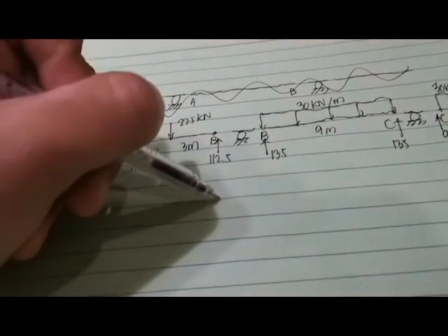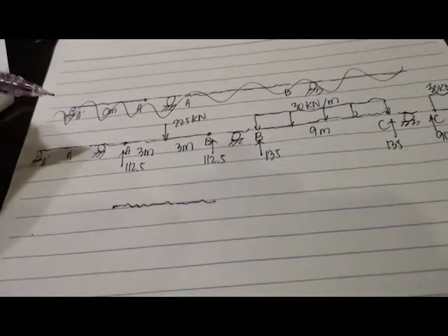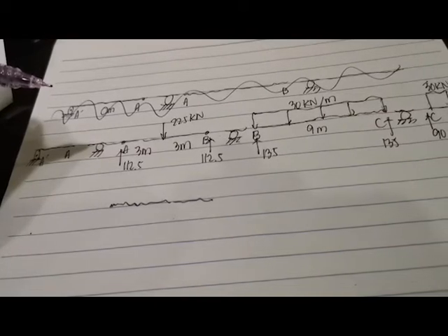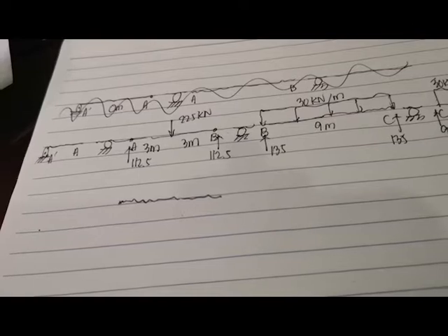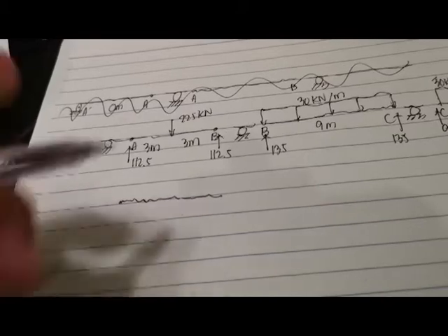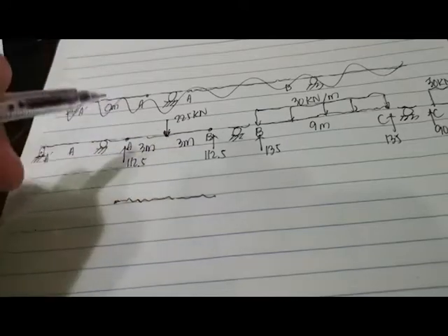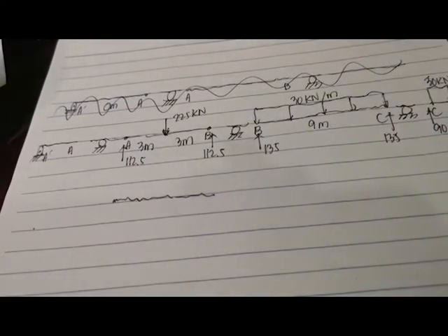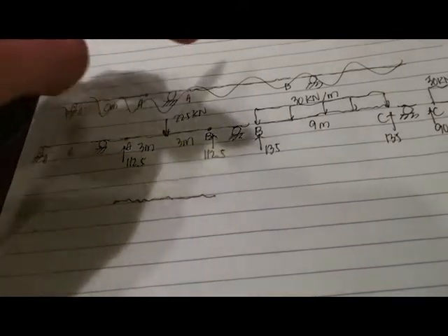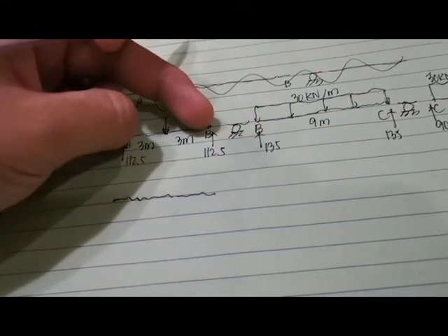Okay? So when computing area and centroid, we need to make sure that they are easy to compute. So they are both easy to compute. Since the load is in the middle, we can do the conventional moment diagram, or we can just use by parts. So I decided to do by parts at AB.